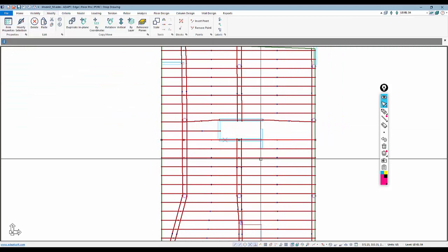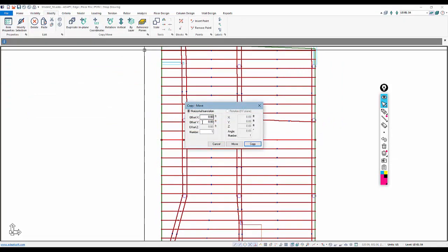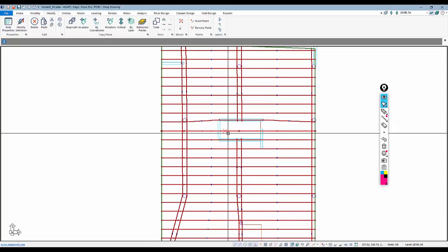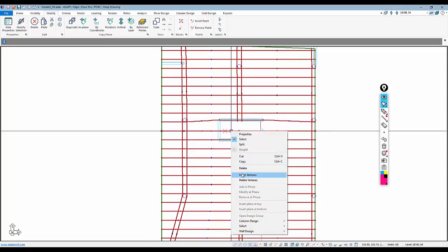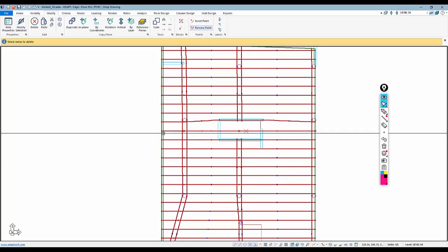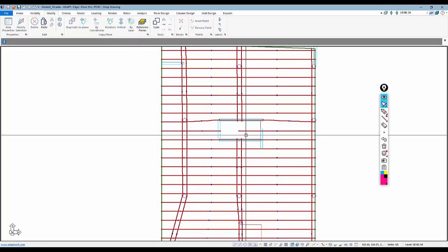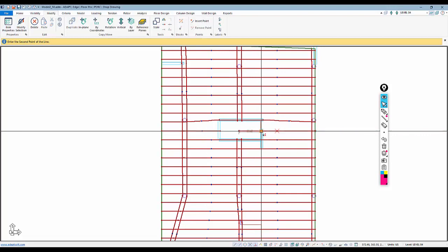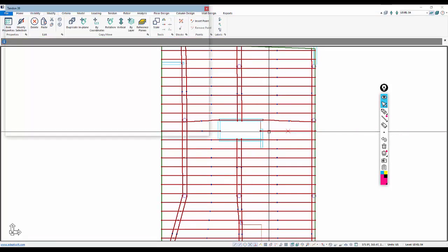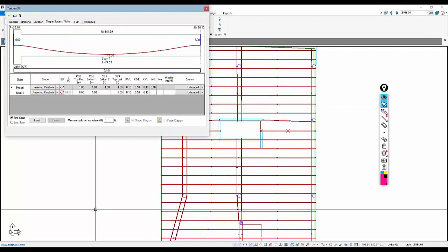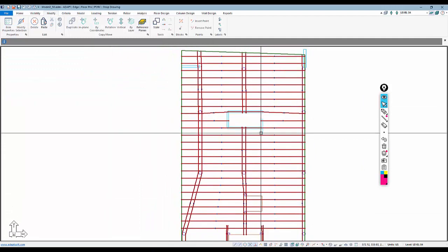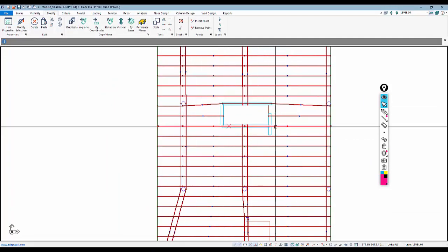I'll take this tendon now and copy that back up one time. So there's a copy of 4 one time, and then I'll delete out some points starting at the left side. So I'll delete point 1 and point 2. And now we have a single tendon on this side. Okay, and that cuts it out of the opening, and we have this one which is basically over the wall.